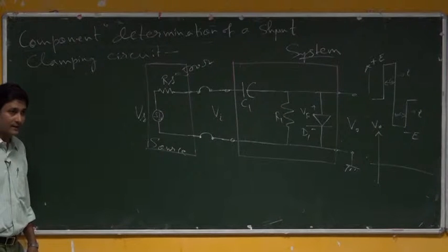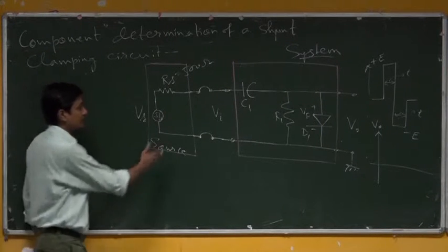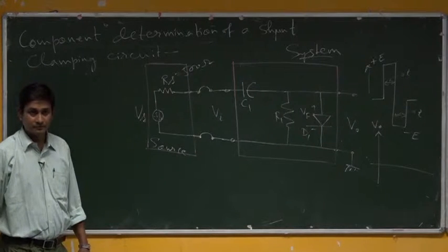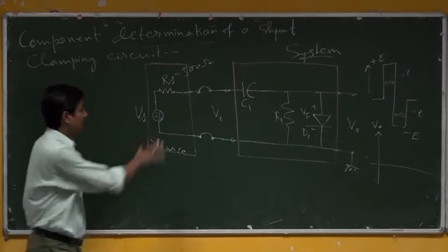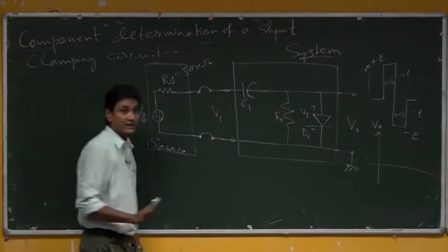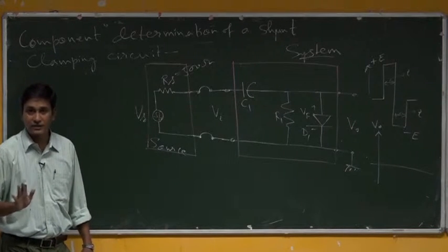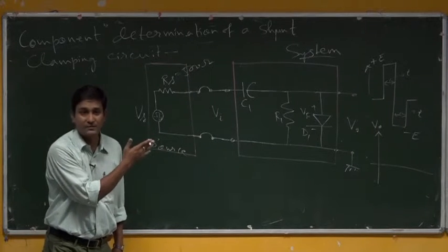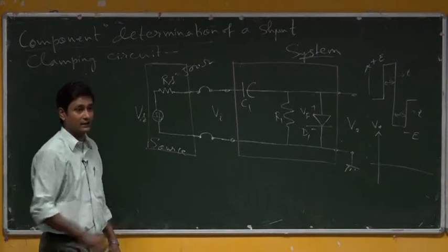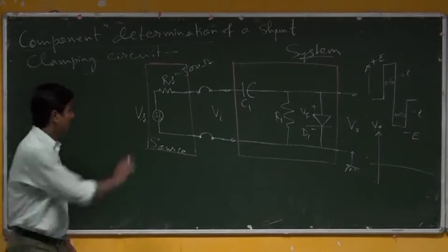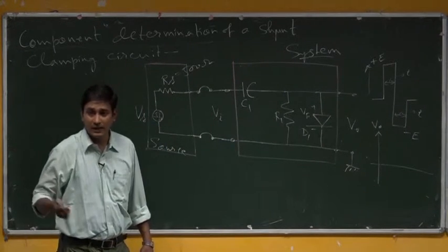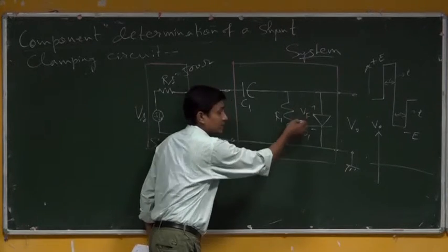Now, if this is the circuit where the input has come in this fashion, what should be the output? We will start analyzing. First, we will see whether this diode is forward biased or not, whatever resistors or capacitors are connected to it. Because first I have to check how much is the maximum possible potential across the diode. Say the full potential here has gone to this, which is quite above the threshold cut-in voltage Vf.